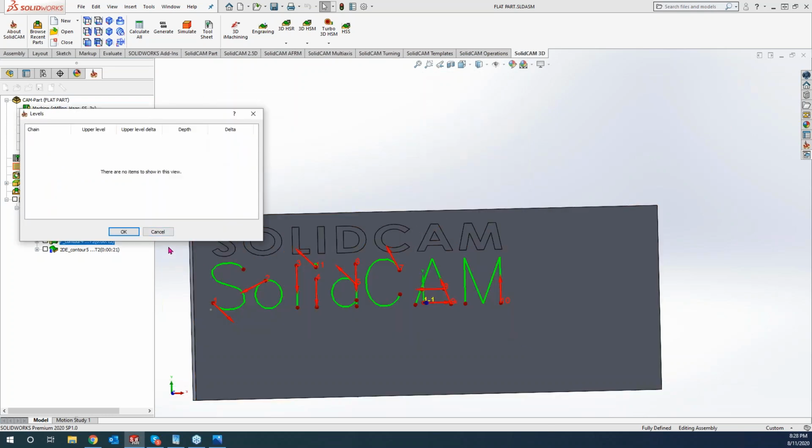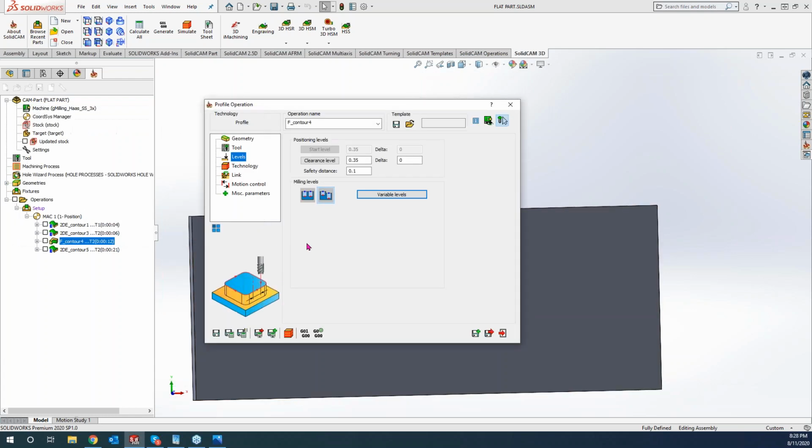But one thing you would have to do is grab this not as text, but as chain geometry. So this would be one chain, this would be a second chain, and it's not going to pull it up through the text option right there. So you'd have to do single line geometry there. Great question.